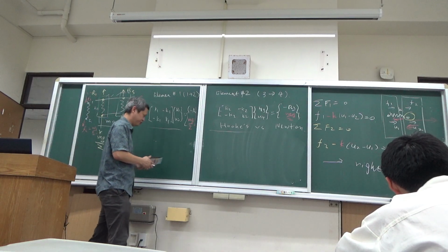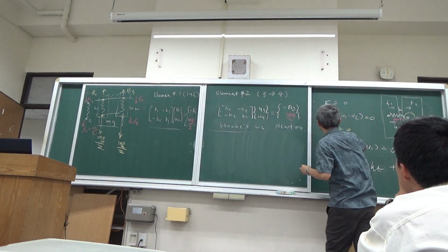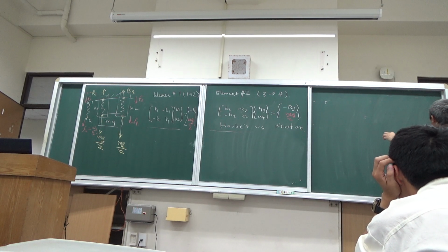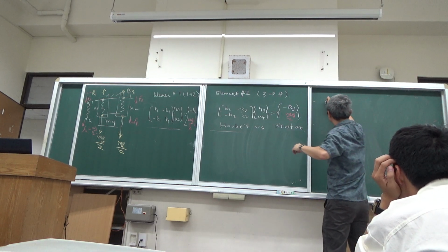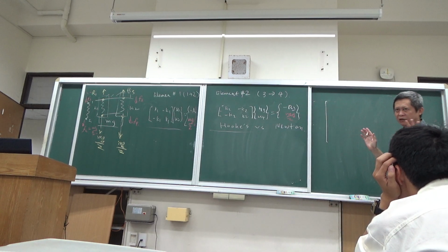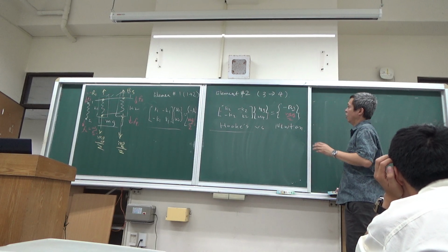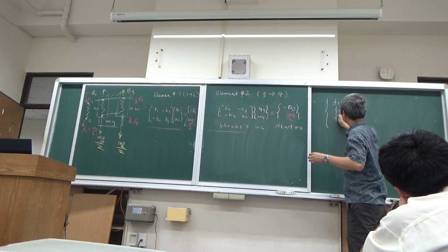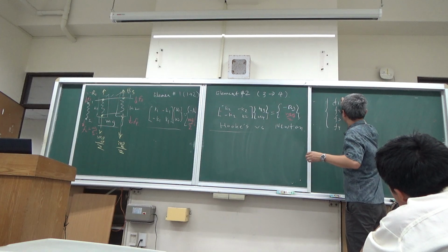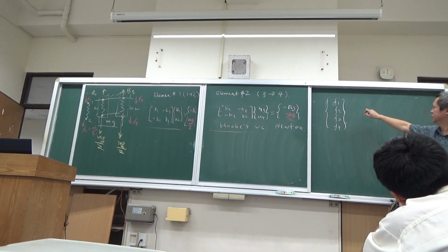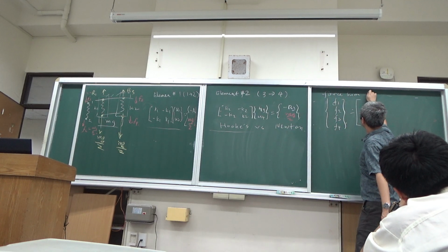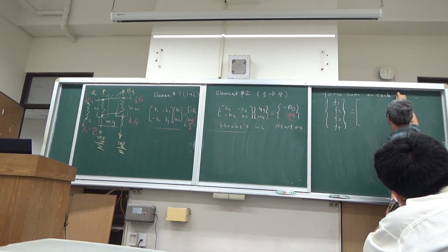If you want to do force sum arbitrarily, you're going to overload yourself. Okay? Please forget about the element assembly in your textbook or whichever textbook. What you did for element assembly is nothing more than writing these force sums on each node.